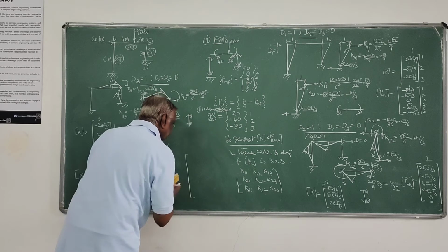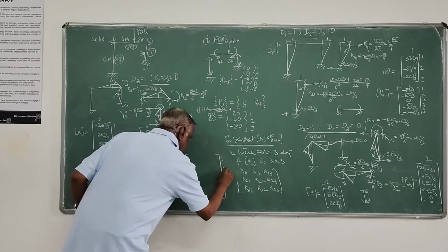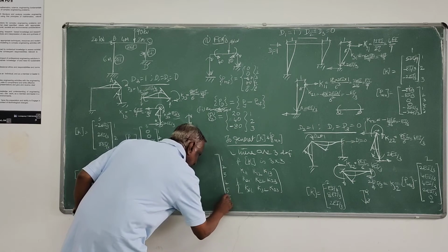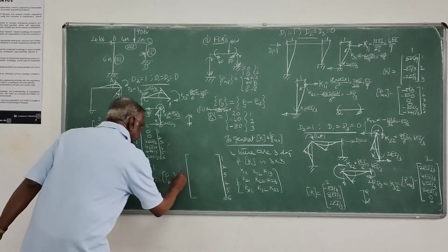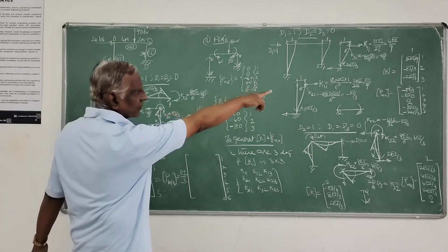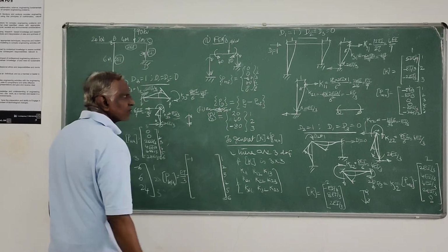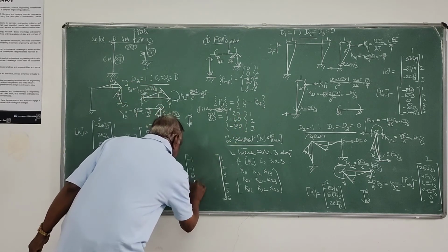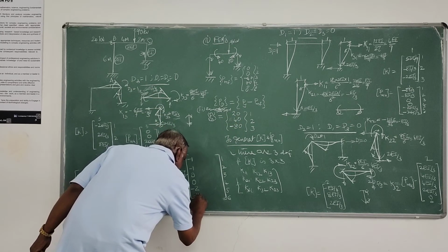And you should not make any mistake. This PMU matrix corresponds to those members' coordinates 1, 2, 3, 4, 5 and 6, member end moments. We have generated that. Here I can take EI by 3 outside. So if you see the first column, EI by 3 I have taken outside. This is minus 1. Then minus 1 again. 0. Next 0, 0. Next you have minus 2, minus 2.